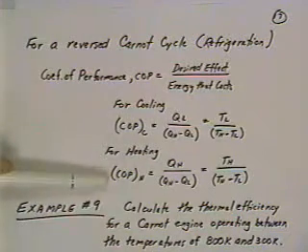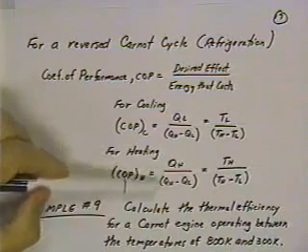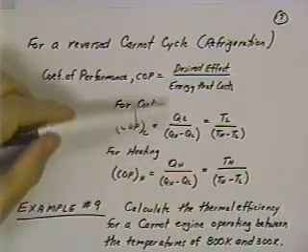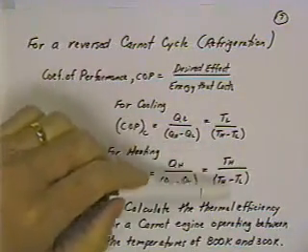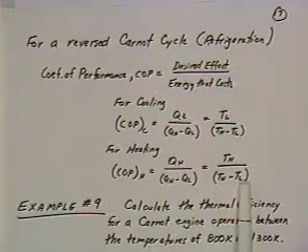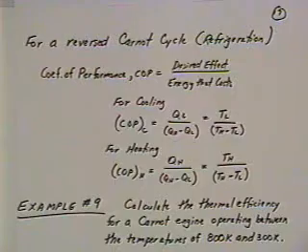And for heating, you're interested in the heat transfer on the high side, QH over QH minus QL. This, of course, is the work term, so the energy that costs you is the work. And so this is TH over TH minus TL. Again, TH minus TL is the work term, and TH is the heating. So you have two terms when you're talking about refrigeration cycles that are important: the coefficient of performance for cooling, defined as TL over TH minus TL, and for heating, TH over TH minus TL, if you're talking about the Carnot cycle.